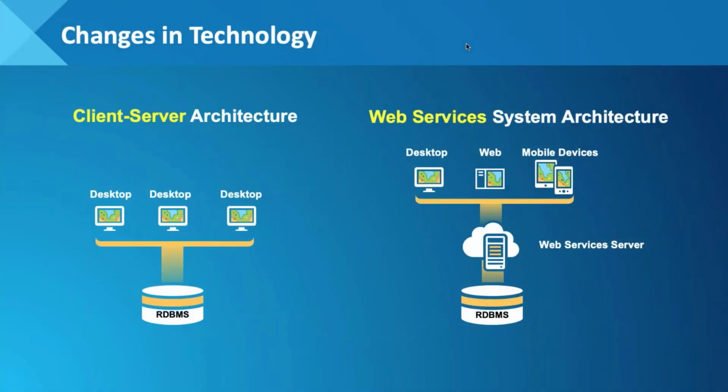One of the important things about both ArcGIS pipeline referencing and the utility network is we now see our software moving away from the traditional client-server architecture into more of a web services architecture. When we move to web services, we're publishing the data from the server, which you're probably familiar with from web mapping applications. We're actually consuming those web services in the editing workflows. So now I can not only edit from, say, my Pro desktop, but I can also do those same edits for a web application or a connected mobile device.